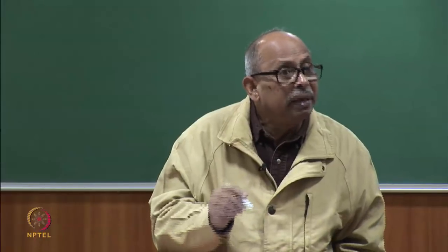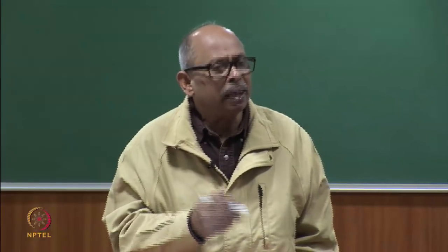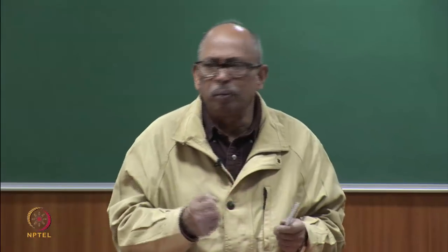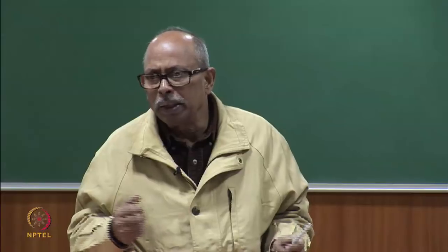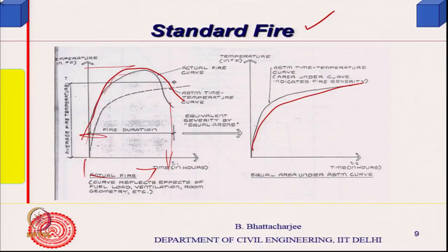Similarly, in case of fire, the standard fire was arrived at by a consensus of experts. The ASTM standard fire or Indian standard fire is basically adopted from an appropriate international code, and that fire is something like this, the ASTM time-temperature curve. What they do is this: it monotonically increases, it does not stop. As time passes, the temperature is higher than in the real fire.